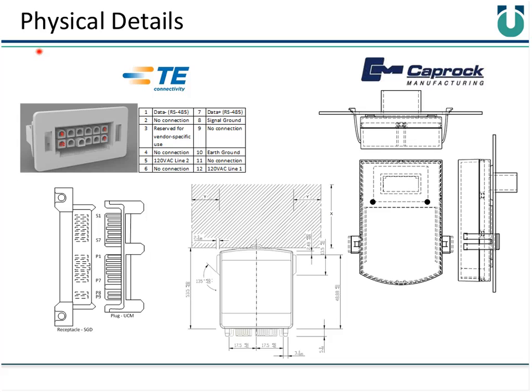As you can see on top left, this is the connector with a little pin layout. Pretty straightforward, and it can take either 120 or 240 volts in one line, or it can actually take two line voltages, so 220, 240 volts, as you can see here, line 1 and line 2, to operate the module. Of course, manufacturers must then take care of applicable UL requirements if you're feeding line voltage into a module. Of course, there's other isolation needed than if you have DC going into it.